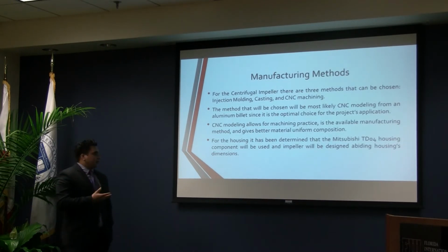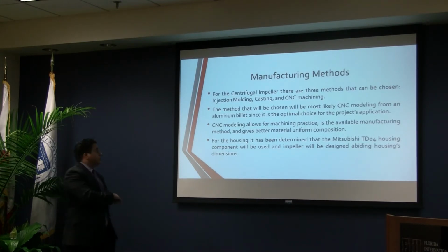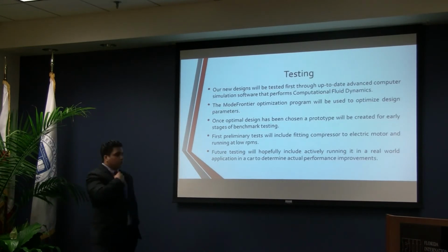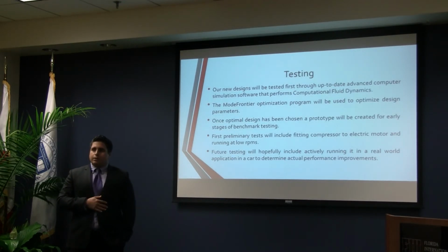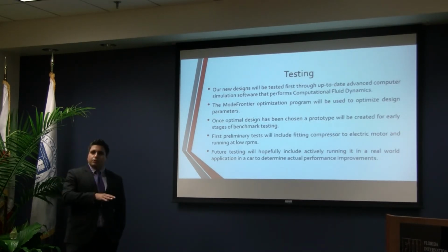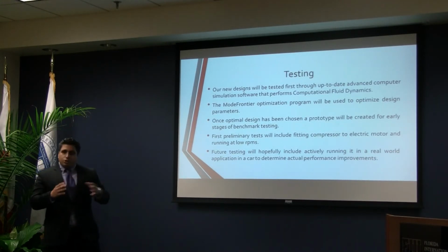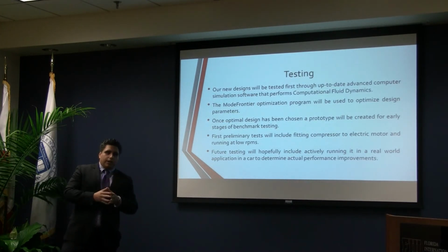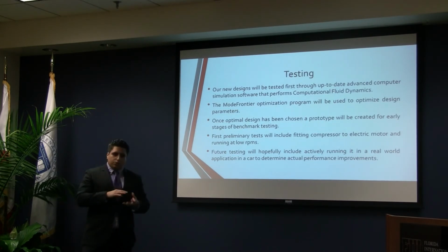Now, for the housing, it has been determined that we will be using the Mitsubishi TD04 housing component, and the impeller will be designed abiding by the housing's dimensions. Now, for testing, we want to first put it through computational fluid dynamics. Then after that, we will put it through the modeFRONTIER optimization program to optimize design parameters. Once the design has been chosen, our best bet is to create the design, make a prototype, then run it and fit it with an electric motor just to make sure that we have all our clearances right and it's running smoothly and not having too much play or anything.